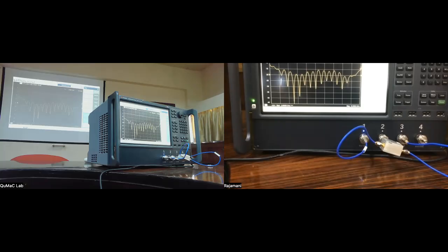So that's why if you now consider this as the operation of the device, that on ports 1 and 2, if you put 2 signals, the sum comes on the S port. In fact, that's why this port is labeled S. It stands for sum. Sum comes out here, and the difference comes out on the internal port, which is basically a hidden 50 ohm port inside.